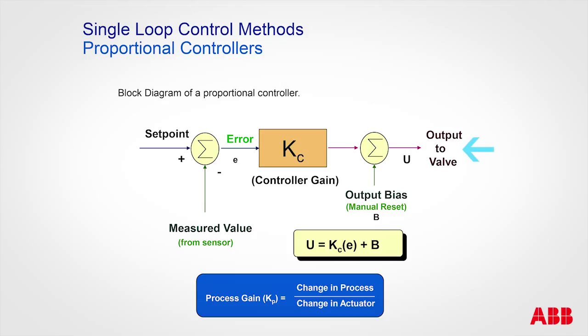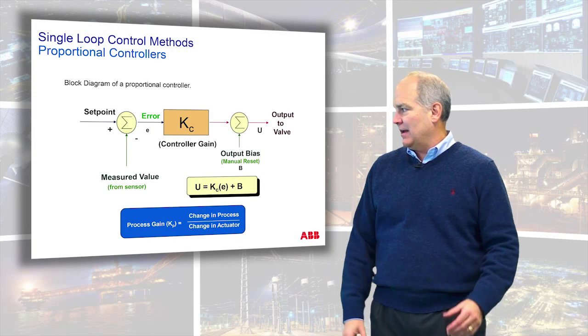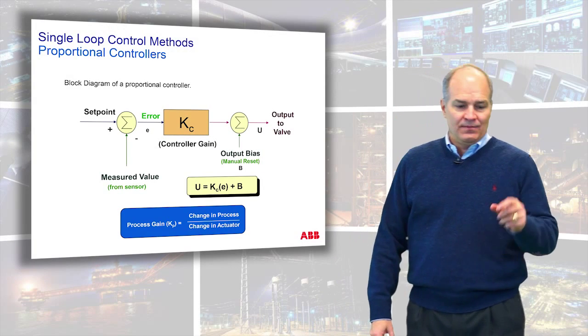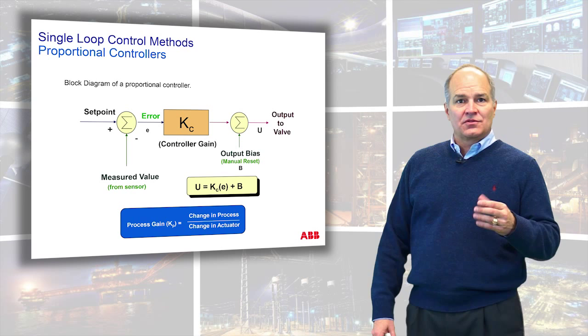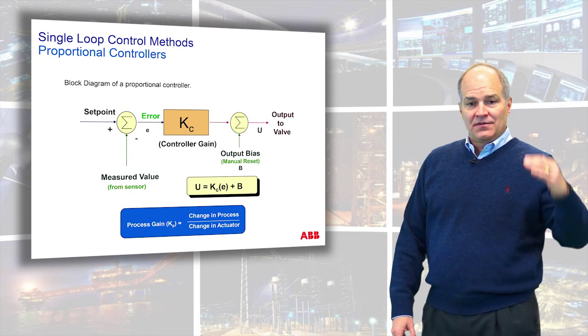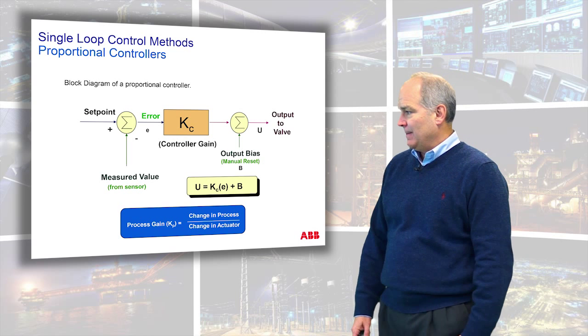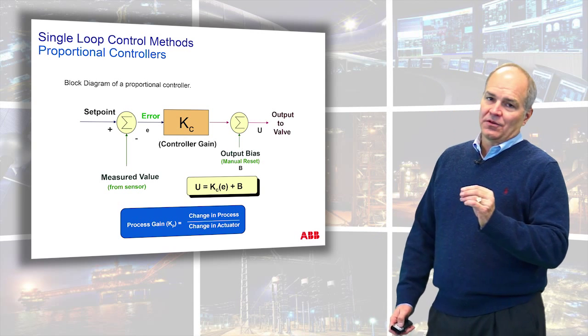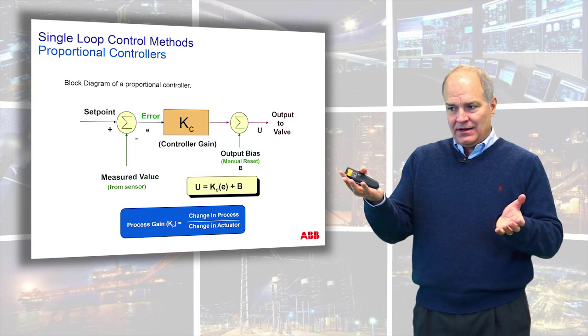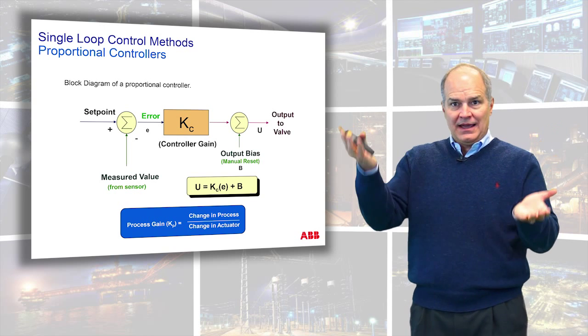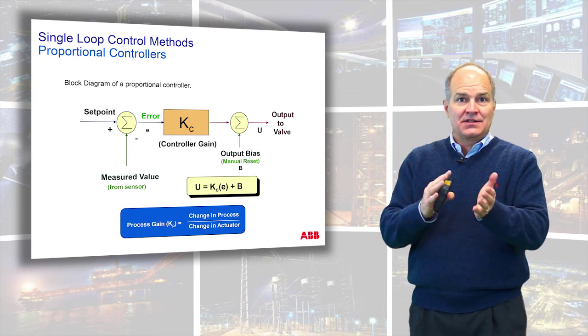And I remember, this is hardly used today, but in the early days, there was actually a knob that they considered a manual reset knob, because proportional-only control would result in an offset. So if the measure was off, they'd go and adjust it and make it 0. And I'll show that here in a little bit. But you can see the fulcrum, this idea that the error is exactly proportional to the output based upon this gain multiplier.